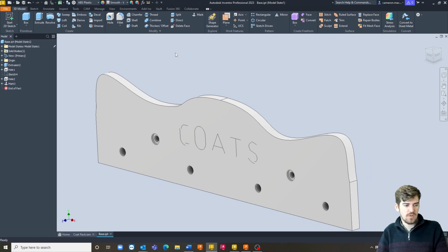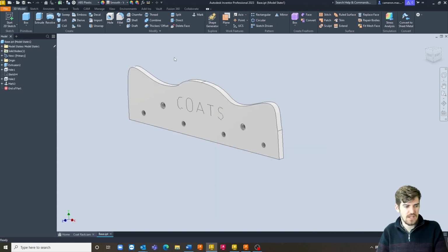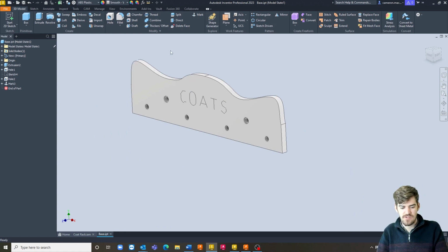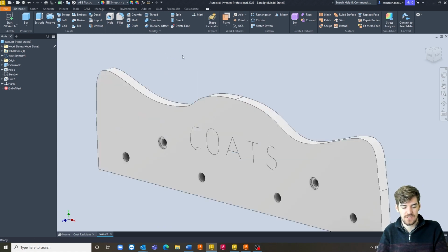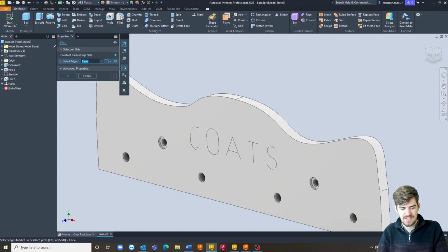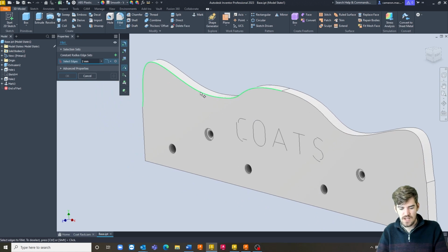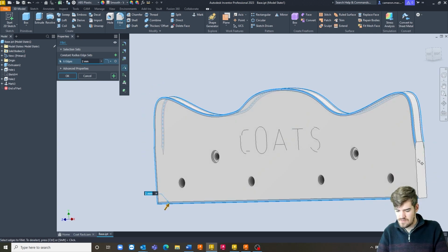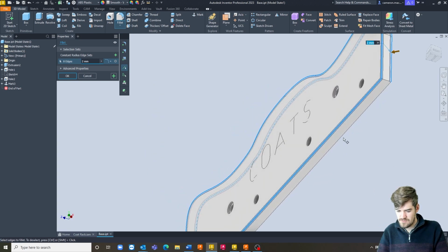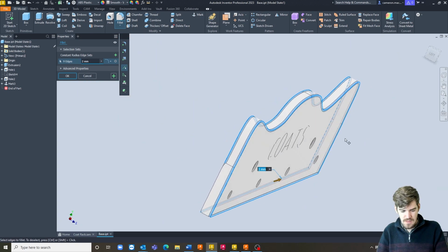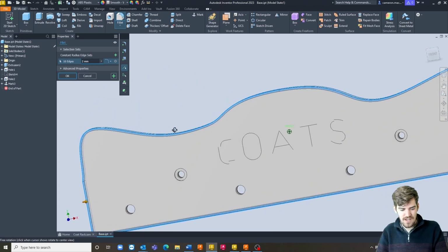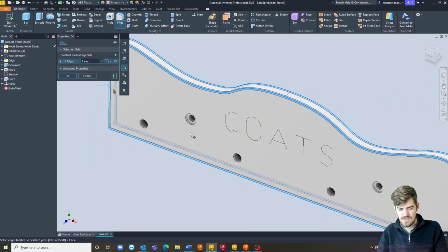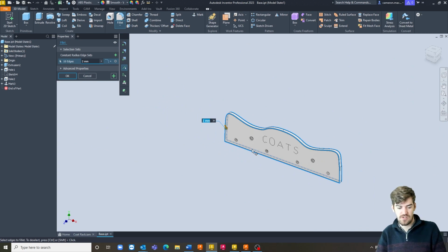One of the other really handy ones that we've got available to us now as well is the ability to add in tolerances during a fillet creation. So what we can do is, if we're placing down a fillet, previously we would have to place down the fillet first and then edit the tolerances inside of our parameters. I'm just going to add a few fillets on here. Last one over there quickly, just for the fun of it. Maybe one more. We've now got the ability to come in and set our tolerances directly from the creation tool.